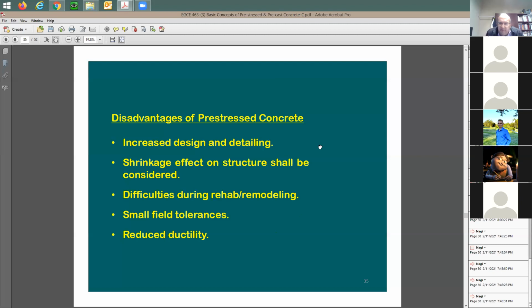Also, let's think about trying to retrofit the pre-stress. How would you do it? You remember the story when I said that, let's say, a plumber would like to cut a hole in the concrete slab and all of a sudden he sees a cable. Now, if you cut the cable and this is an elevated slab, not a slab on grade, this is going to be big trouble, because what's going to be supporting the slab in this case? You cannot substitute the pre-stress. But with conventional rebars, you can attach steel plates or you can use FRP easily. So it is very hard to make changes later on. And also in the field, when you apply a certain amount of tension, the quality control really needs to be high. Otherwise, you can lose the pre-stress easily, and this is going to be big trouble.